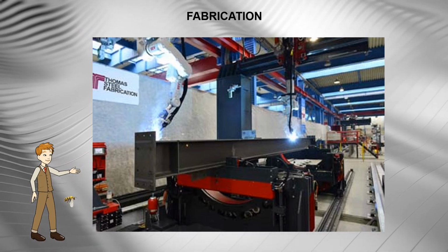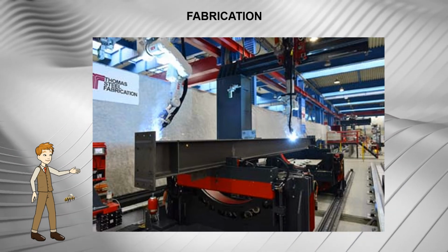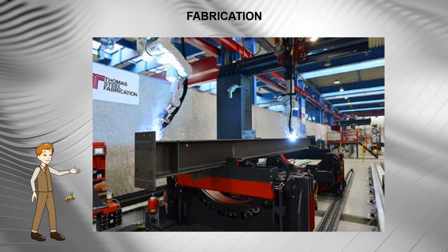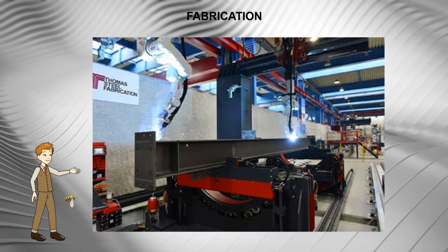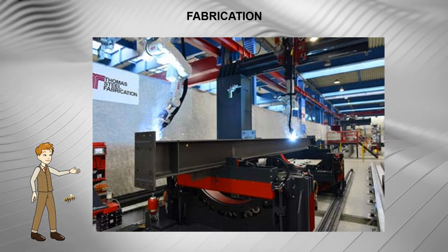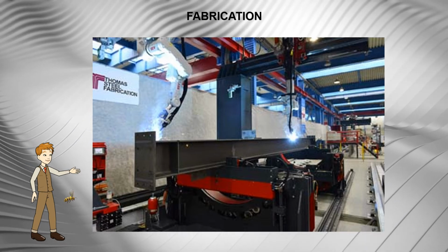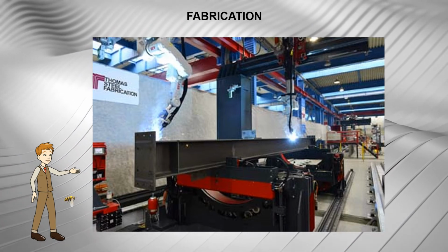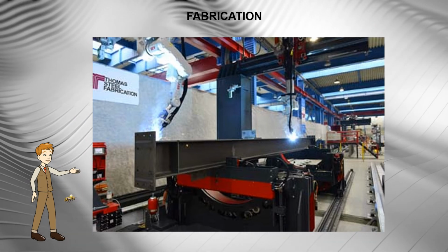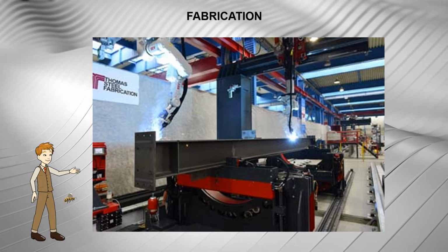When large prefabricated trusses are used, it may be necessary to provide lifting points or eyes, which are located to minimize stresses induced during lifting. All parts which are shop painted need to be handled very carefully to avoid damaging the coating. Lattice girders are made up of long, basically slender members and may therefore be subject to severe distortion due to welding unless care is taken during the fabrication process.